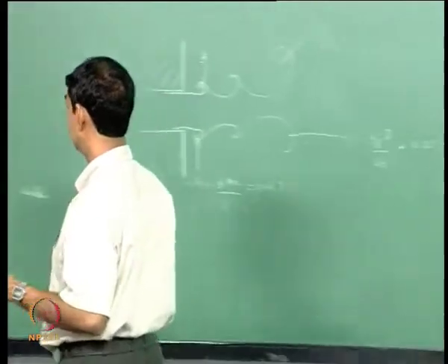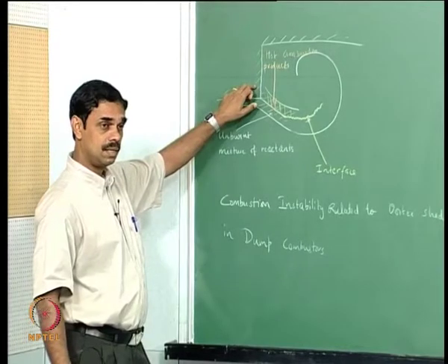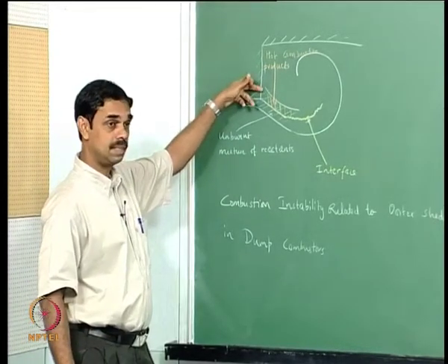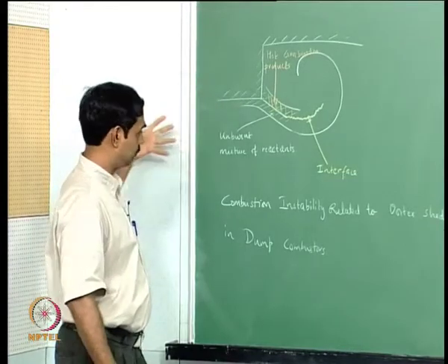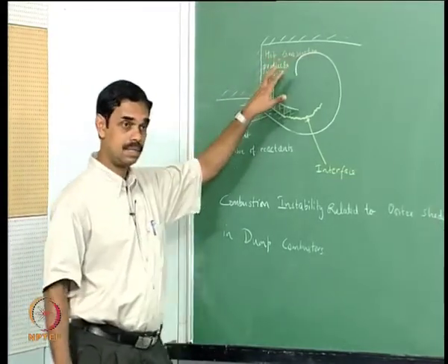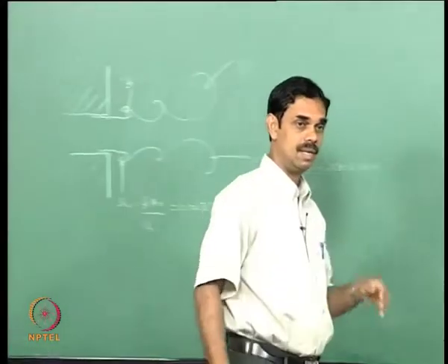So if it is a diffusion flame, you will probably inject somewhere here, many times you inject at this step or slightly behind the step, and if it is a premixed flame, fuel and air are coming together, but you have hot radicals here. In either case some scenario like this would be valid.